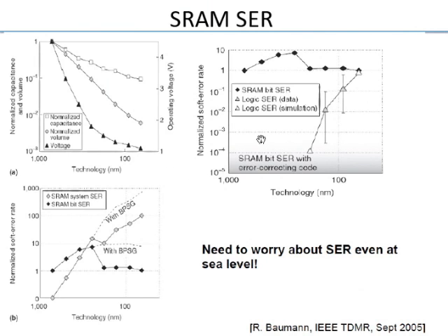Of course, this is also a problem in the case of DRAMs. Imagine for DRAM it is even worse because you have only floating capacitors in a dynamic RAM. We'll study that next. So in a dynamic RAM, even if you shrink it, you try to keep the capacitance the same by using a lot of material tricks, high K dielectrics and so on. So the message here might not be very apparent right away from these graphs, but actually if you look here,